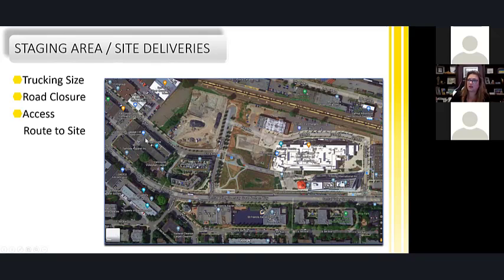So the constraint of the panel is unfortunate. We would have preferred to go as large as absolutely possible. Trucking makes it nearly impossible for us to work. We can't actually encroach on this property, and to make this turn, we can't get in here unless we're under 50 feet. And so our 53-foot panels no longer work. Then we have to talk to the city about doing road closures. We're going to be taking our truck in, and we're going to be backing into the ramp.